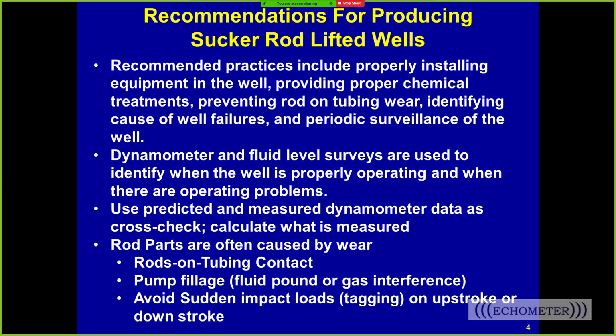When we talk about producing rod lifted wells, it's important to have recommended practices that improve the operation of the well. Some of those recommended practices are installing the equipment properly, preventing corrosion, preventing rod on tubing wear, and there are all different kinds of ways to do that. Also identifying why something broke or failed, and then periodically surveying the well. And then we talked a lot about maintaining a full pump, and we'll talk about that also during the class.